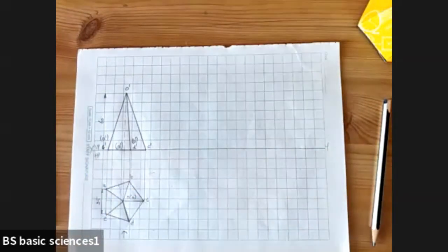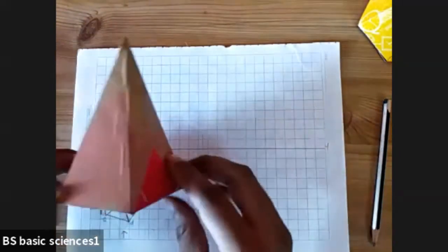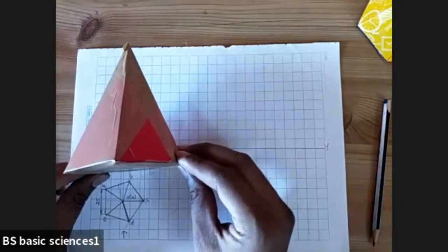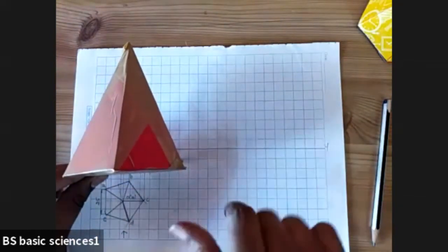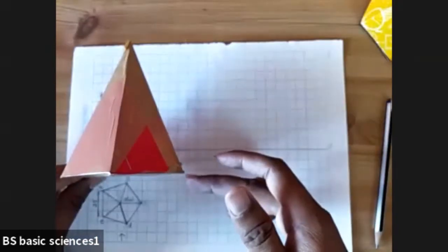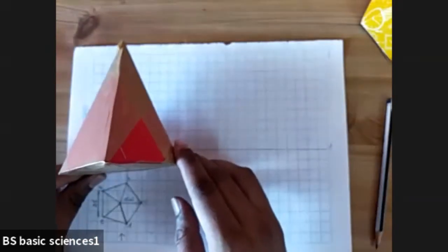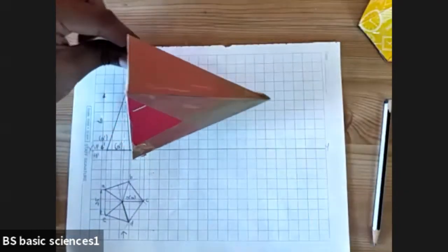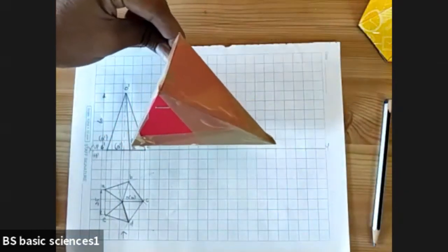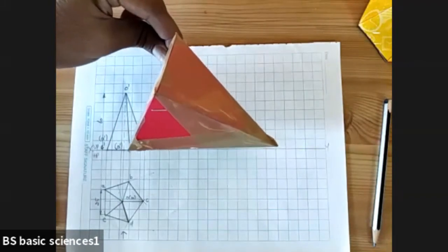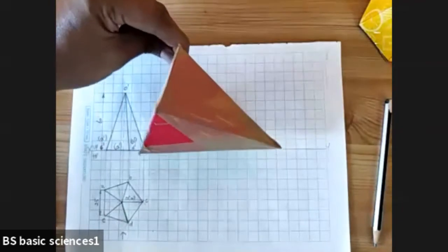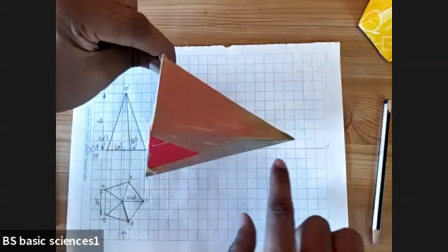Second condition. With respect to the front view, I'll show. See, this was the front view. What he is telling in the second condition is that you have to incline this with respect to the slant edge. See, what I'll be doing is I'll start inclining it with respect to the slant edge until it touches your XY line. So this will be your second condition. The pyramid is made to sleep on HP with respect to one of the slant edges.